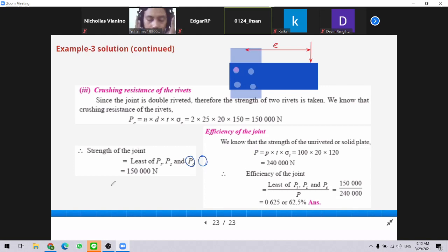How does rivet compare to weld and bolt, sir? Rivet and bolt actually have similar analysis, because the way they resist the load is the same, and the joint failure mode is also the same.